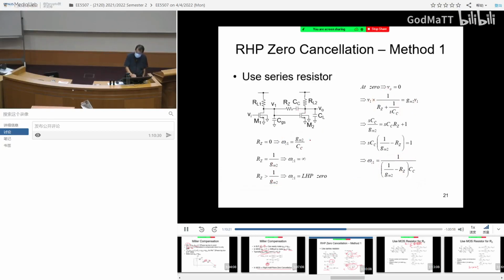Although it can help, we can still design a stable system, but not as good. This helps you remove the additional phase contribution. So that is good. It will help you improve the phase margin. This is even better. It not only removes, it does more than that. It introduces phase lead. So you make the system have better phase margin. So if we apply this guy, this is what we call lead lag compensation. If you apply this guy, it becomes lead compensation.